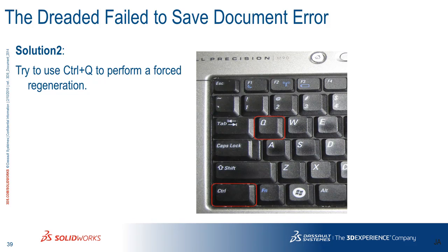Try to use a control Q. Perform a forced regeneration of the model. See if we get a rebuild error at that point in time. Could have a rebuild error with our file.